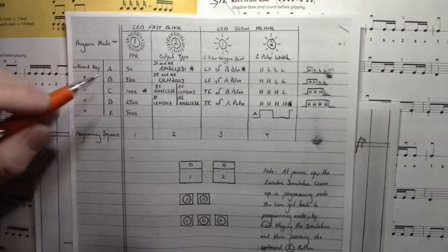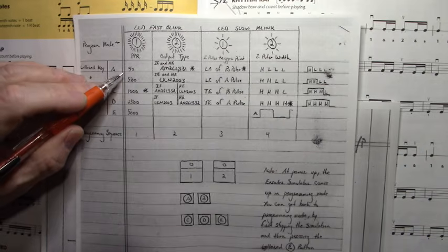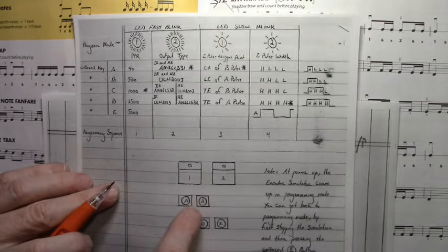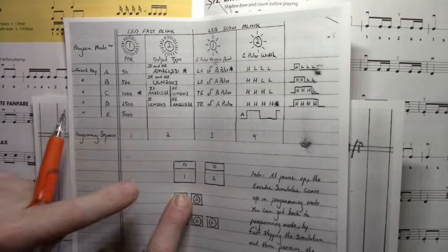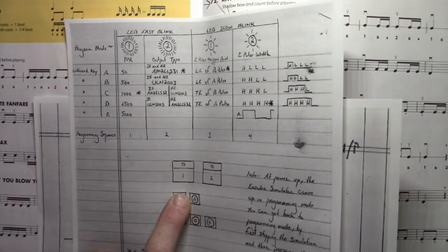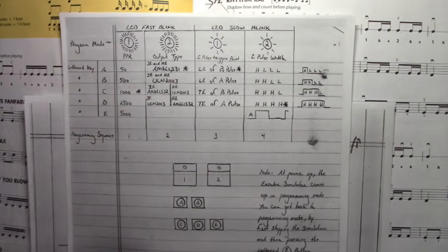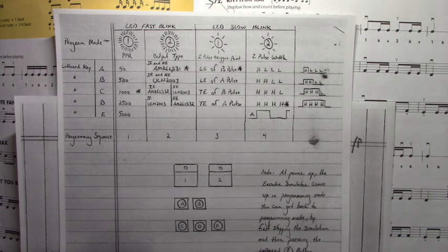So for instance, if you wanted to set your feedback simulation for that encoder output to 50 pulses per revolution, you would push the A button. Here's A, B, C, D, E. You'd push and hold that button and then push the number 1 switch. And that would set that output to 50 pulses per revolution. By pulses per revolution, what I mean is that your first occurrence of the home pulse, and then you would have 50 pulses until the next occurrence of that same home pulse.